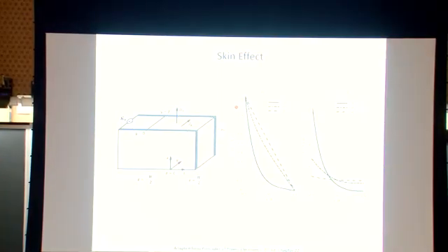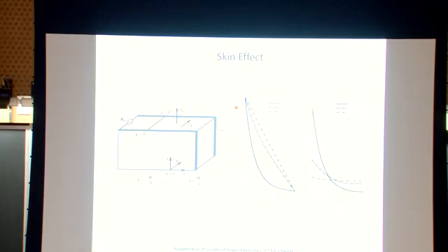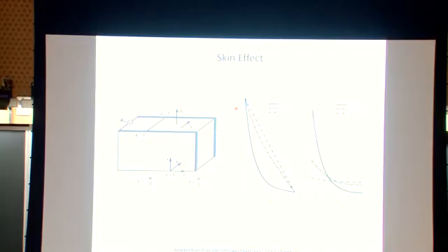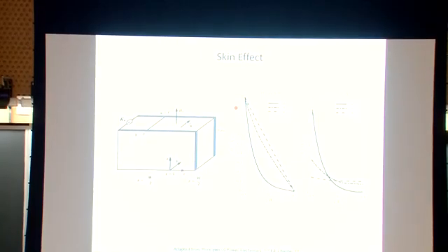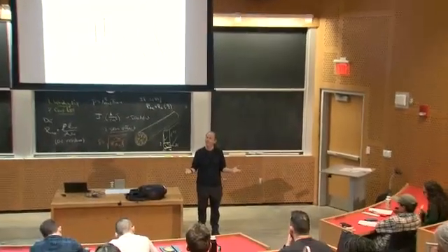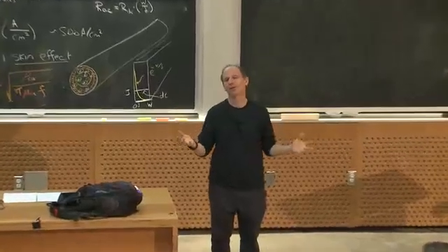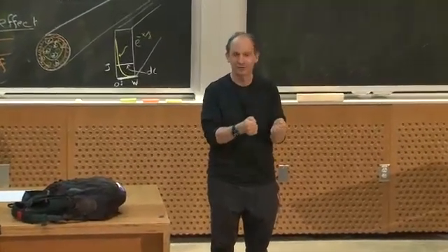Thanks, Steve. So you could see that the skin depth, that's the exponential length constant with which things decayed, was about a factor of 2 different in those two examples, because the frequencies were about a factor of 4 different, okay? So what do I hope that you're going to take away from that? What I hope you're going to take away is you're going to think when you design something, oh, if I'm trying to carry high frequency currents, okay, I better think about how big my conductor is relative to the skin depth.